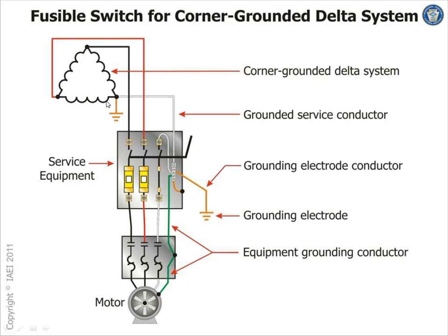So you have an ungrounded system and there is a transient in your building that keeps burning your VFDs. One solution is to take phase B, typically, and tie it to the ground. So now you have a so-called corner grounded system. And then this is a grounded conductor. This is so confusing and it will burn a lot of equipment for the maintenance guys, because imagine an electrician walking in here on a panel and looking at this white conductor.